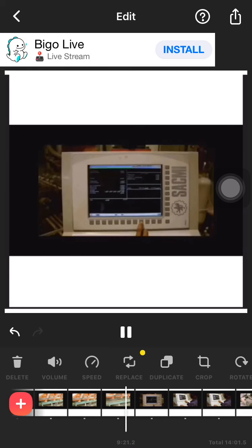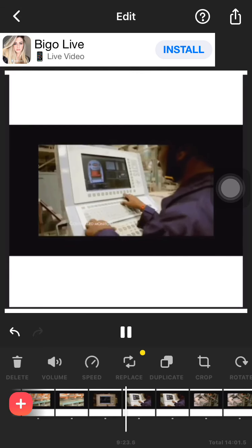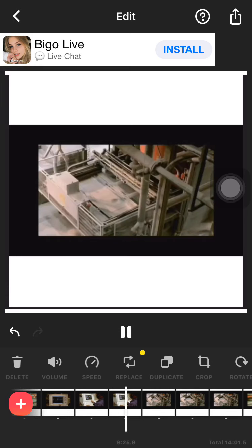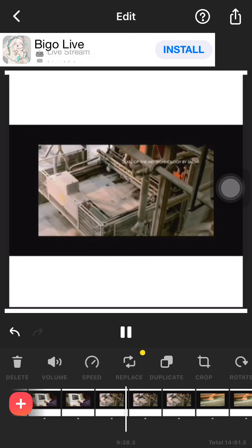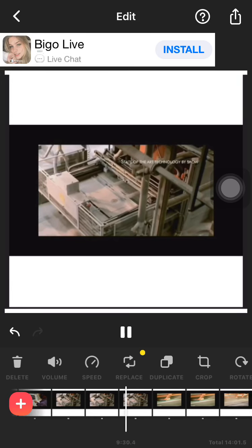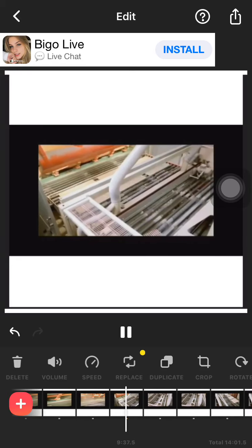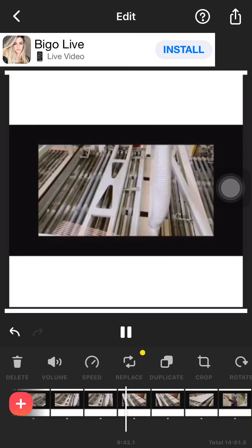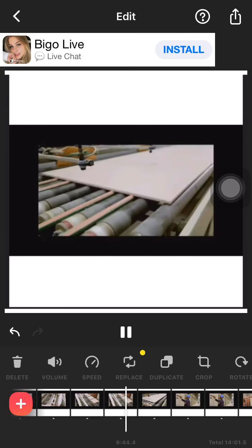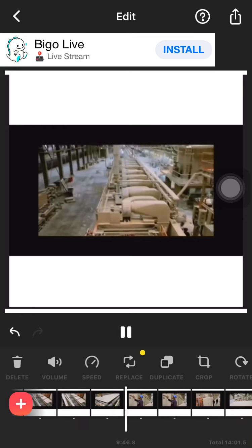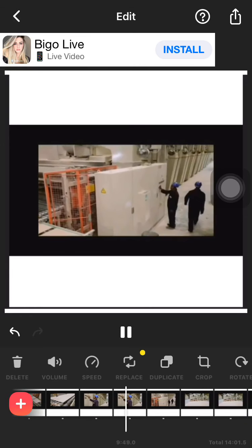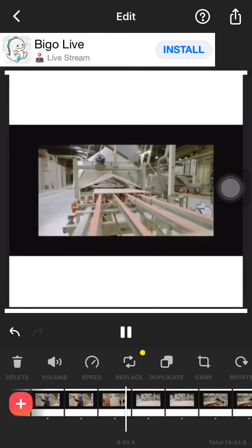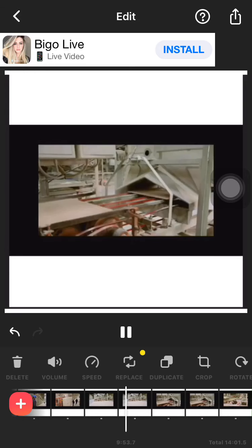Made by SACME, the world leaders in tile technology, our fully automated tile press is capable of shaping tiles in a range of sizes and shapes. The machine presses the powder at 400 to 500 bars of pressure to create a raw green tile. This green tile is then processed in a dryer, completely removing all moisture content, making it ready for the processing that will truly give it color and finish.